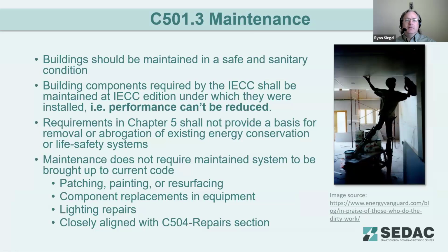So as far as maintenance, the code talks about building maintenance. Again, the importance here is that we're in a safe and sanitary condition over the lifespan of this building, and that the building components need to be maintained over time. So you can't reduce performance through maintenance. If you make a wall repair, for example, you can't remove the insulation that was in the wall and then not put it back. Obviously, you can put new insulation back in its place from the insulation you removed, but you cannot leave it just uninsulated.